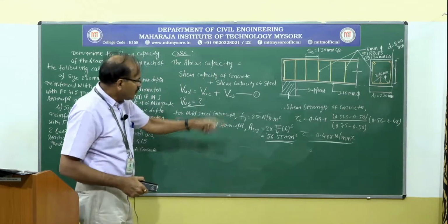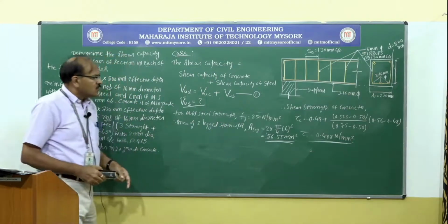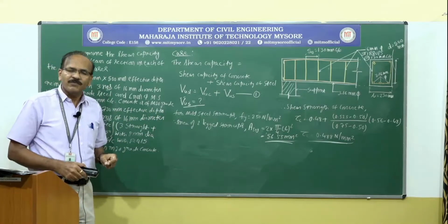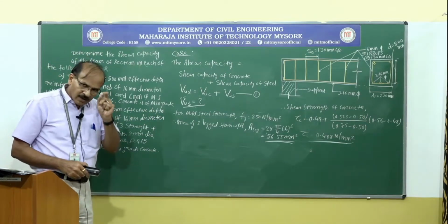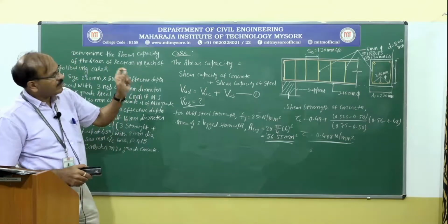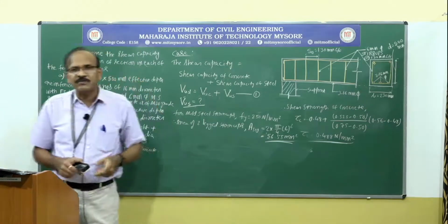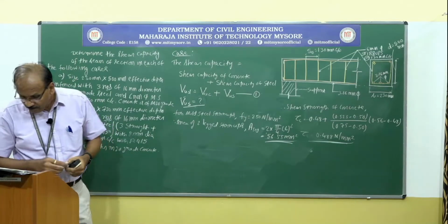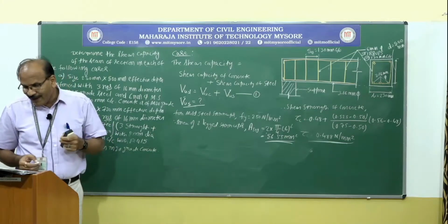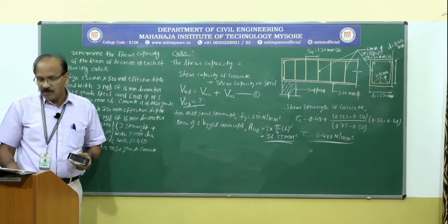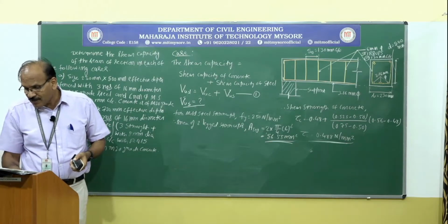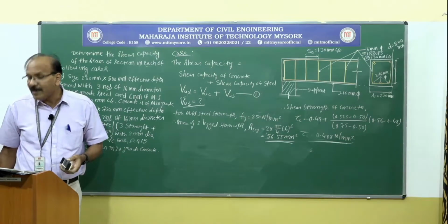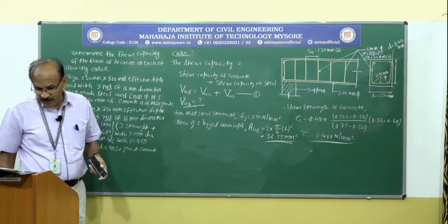Okay. So, once we have the ASV value, we need to find out what is the shear capacity of the reinforcement. So, again here the shear capacity of the reinforcement means shear capacity of the stirrups. Again, if you go to page number 73, under 40.4a for vertical stirrups, we have VUS equal to 0.87 Fy ASV D divided by SV.